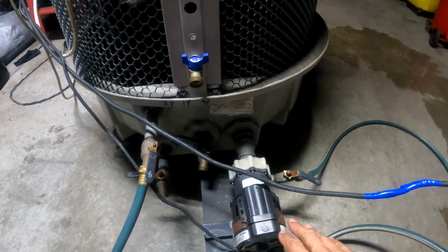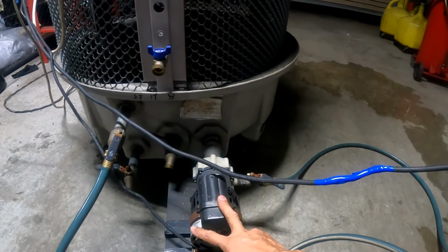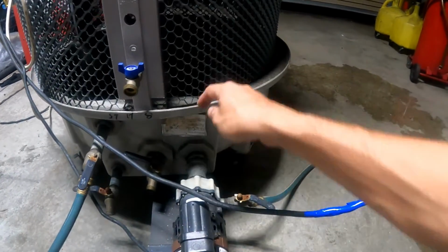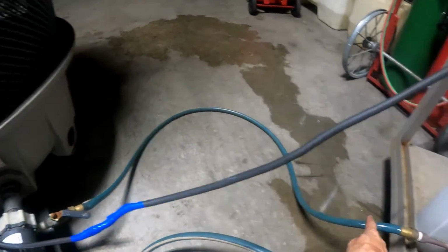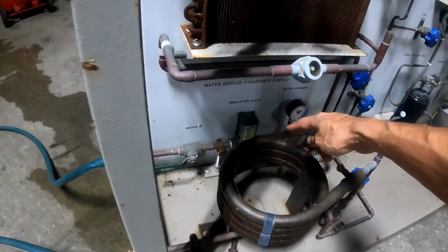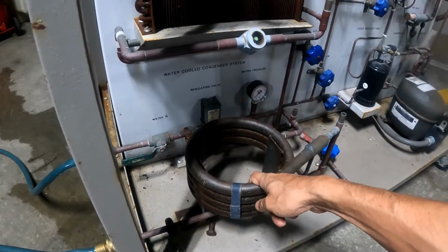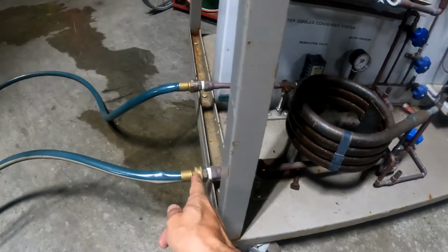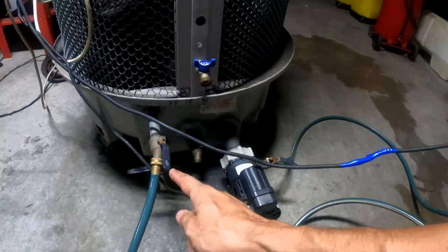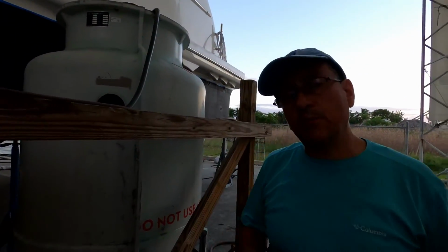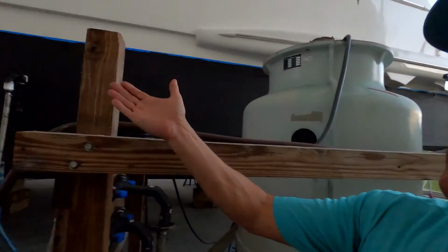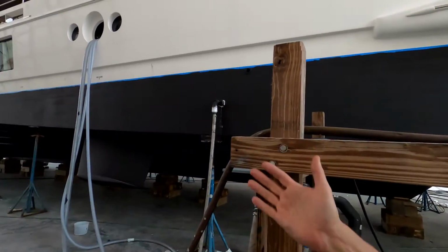This is the raw water pump, similar to the raw water pump used in marine applications. The pump suctions the water in the middle and sends the water with high pressure, and the water enters into the coil, and the water returns and enters again into the tower, and the cycle continues and continues. The cooling tower is another important equipment used when you have the boat outside of the water in the marina for service.